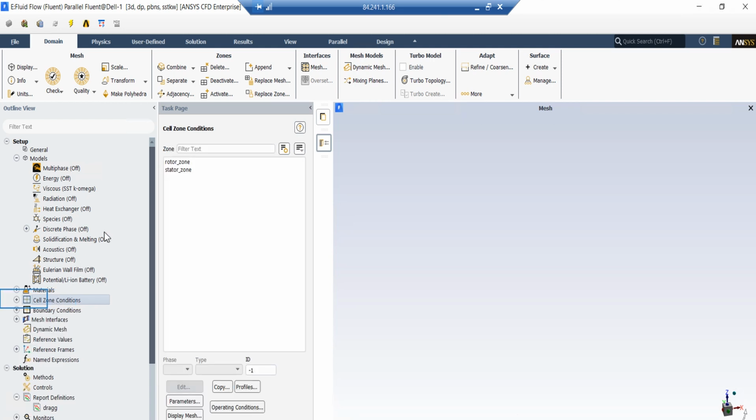As a good practice, it is advised to start the transient simulation with a previous steady state simulation, which is converged with a situation close to our transient simulation. For this specific simulation, to simplify our convergence, we could start with a steady state frame motion setup, and after we've reached a satisfactory partial convergence, we could copy our frame motion simulation to a mesh motion simulation using the copy option inside the cell zone.